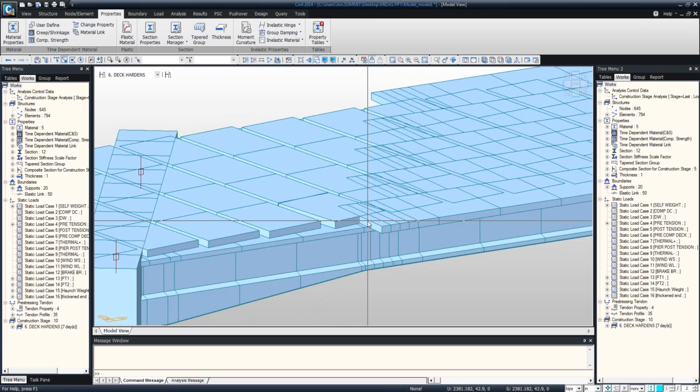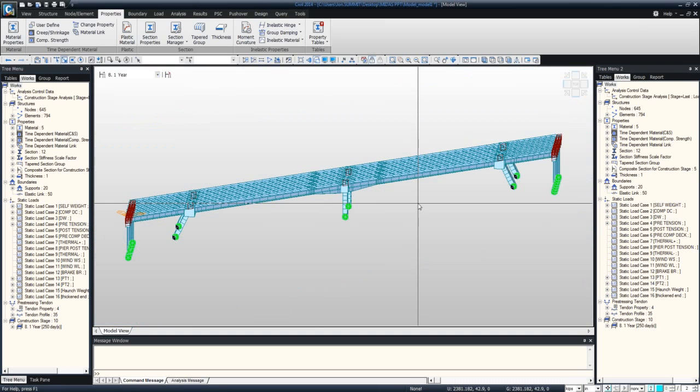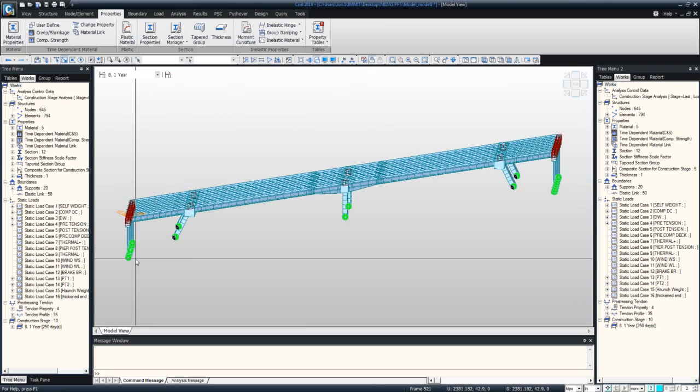So this is my grillage elements. That's distributing load transversely. However, they are weightless and don't allow any dead load. And then once we're up to just aging the structure, this is where the boundary conditions become stable, and this represents the structure in its final state.